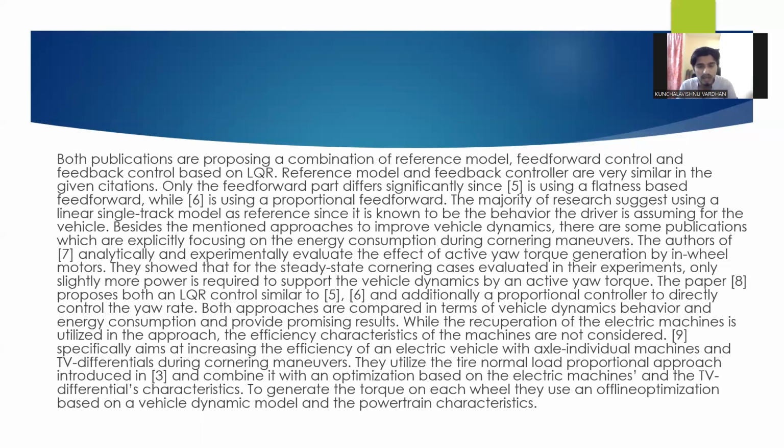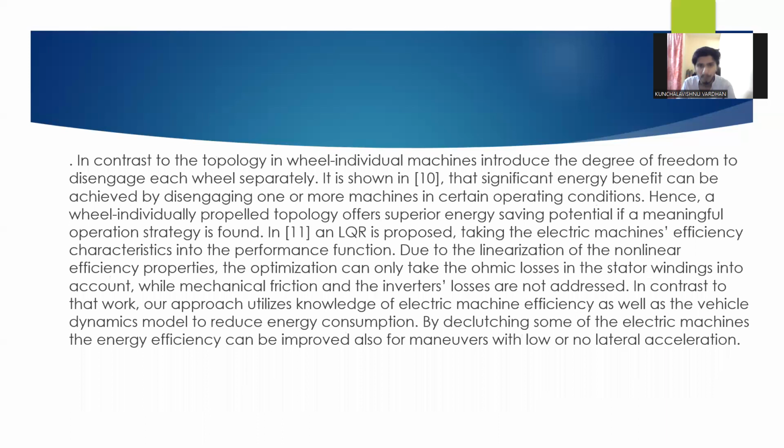They utilize the normal load proportional approach introduced earlier and combine it with an optimization based on the electric machines and the differential characteristics to generate the torque on each wheel. They use an offline optimization based on a vehicle dynamic model and the powertrain characteristics.